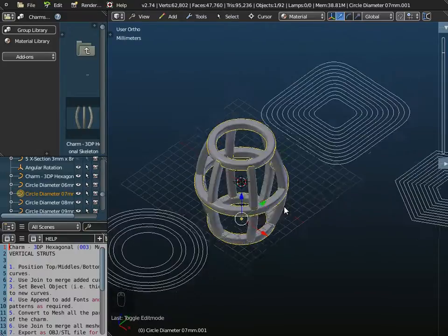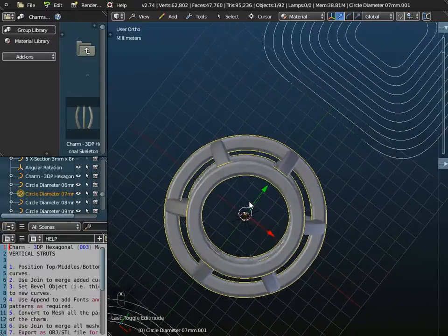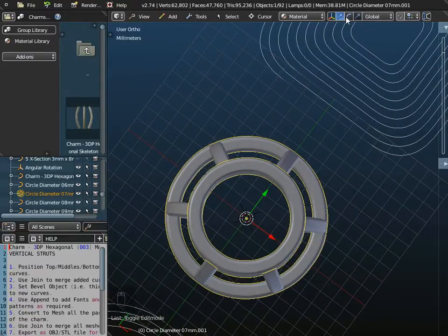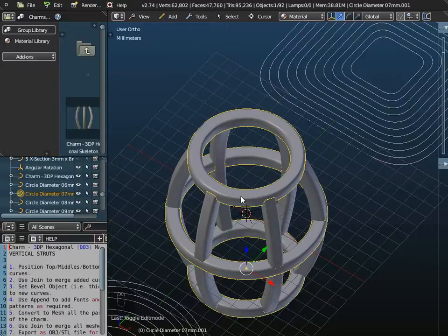Now I could have actually created a different diameter on the top here than the default size. The default size, you'll notice if I measure it, is 6mm. If you desperately want this as 5 or 4mm, you could change the, let me just open up the properties panel again.